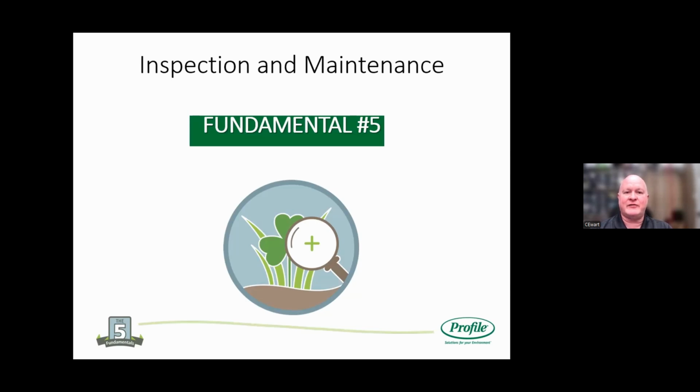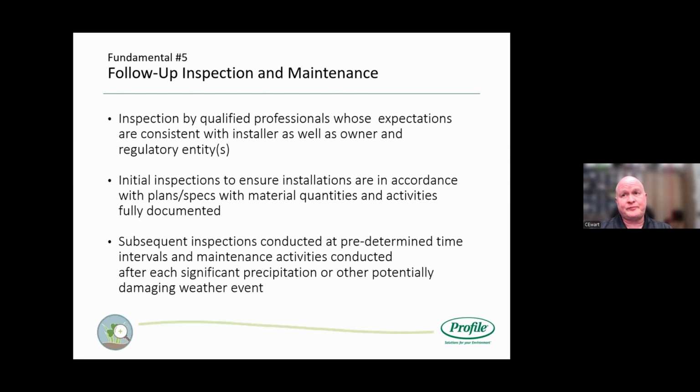So go check it after the first major rain event and look for the weaknesses and the failures on the site, because it's a little bit like pulling a string on a sweater. It's very easy for the whole thing to unravel, but if you can take care of just stitching that string in place, then you don't have so many problems. So inspection and maintenance is very, very important.